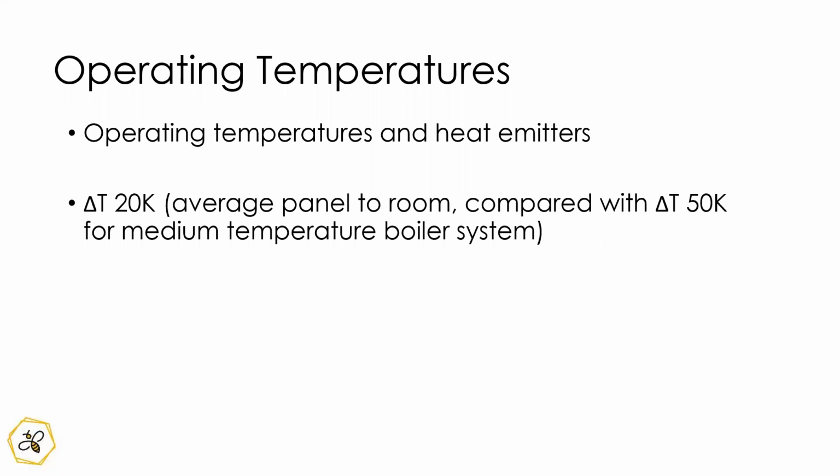So you can imagine for the same surface area and water flow through your radiator system, you're just not going to get the outputs that you're used to. And that's why we talked a little bit about retrofit in the last session, that to really get the most out of your heat pump system, you should be trying to reduce those demands of heating.